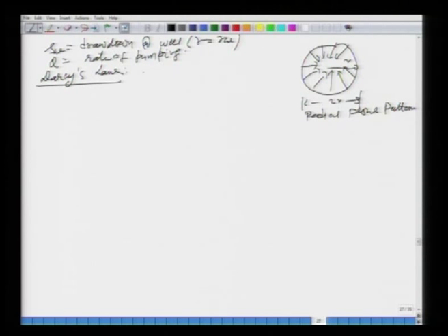What will be the radius? Everything is steady, aquifer is homogeneous, isotropic, K is constant in all the directions, right. So, you have, let us say, VR is the radial velocity towards the well, okay, in any direction. That will be equal to what? You have K dH/dr, isn't it? As you are going towards the well, this is the velocity which is constant.